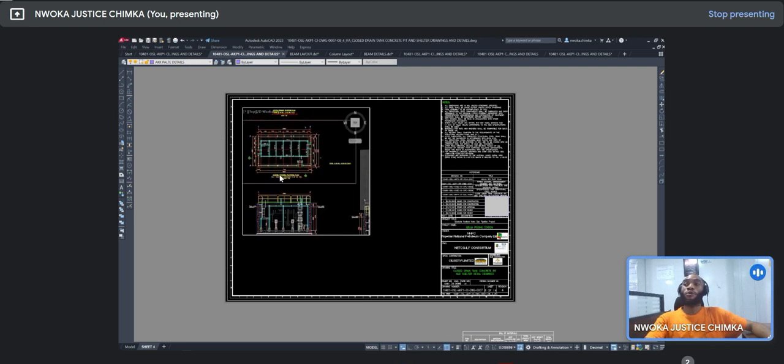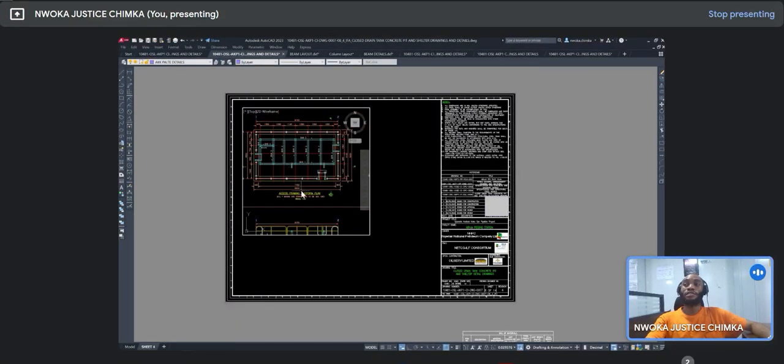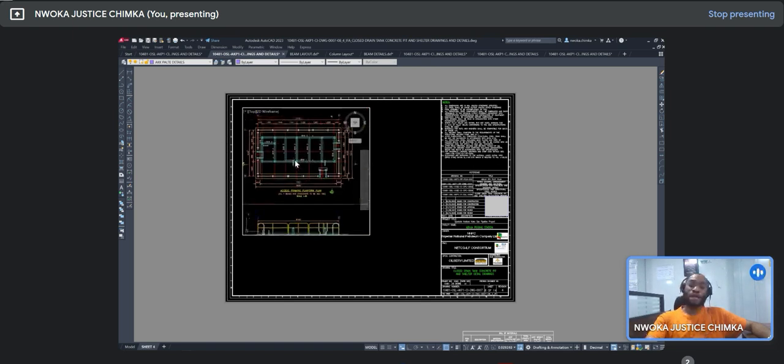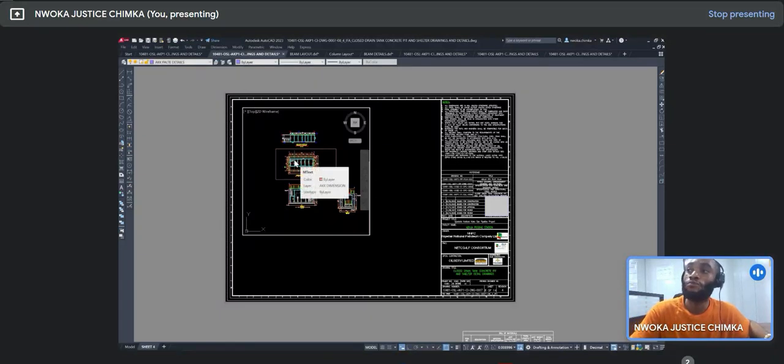Okay, now I have already worked with scale on my drawing. So I want to now bring this drawing to a scale of 1:35 into this viewport environment. So right now I have to type what? Z simply means zoom, enter, and to now work with scale, I have to do what? I type 1 over 35, which is the scale which I use for that drawing. Okay, 35, and then I'll press enter. You can see that it has now zoomed out to this.